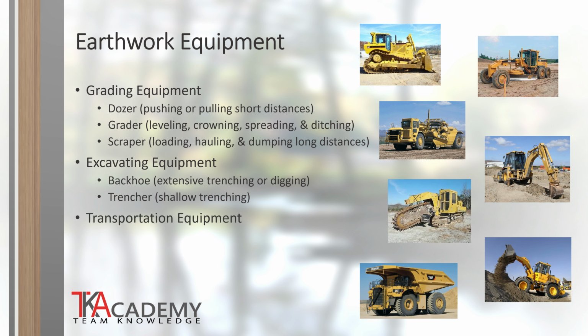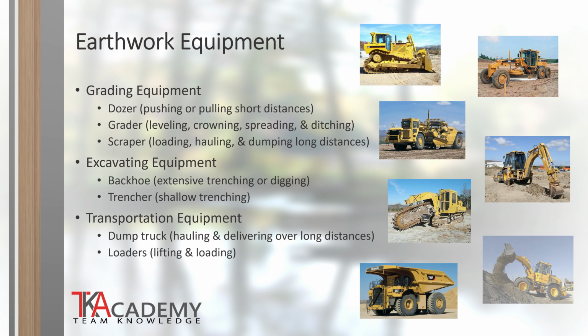Transportation equipment for moving soil over long distances include dump trucks and loaders. Dump trucks, obviously, are for hauling and delivering over long distances or between project sites. Loaders, which have a large scoop on front, are used for lifting and loading earth materials, typically into the dump trucks.